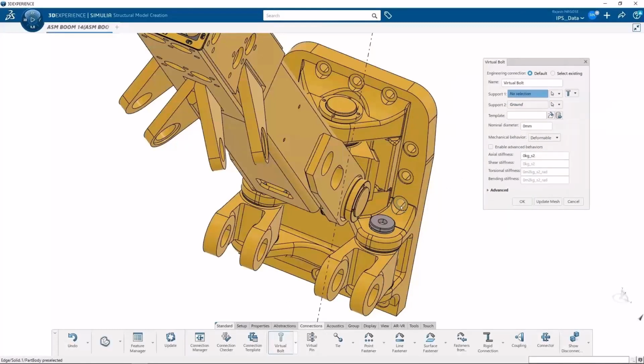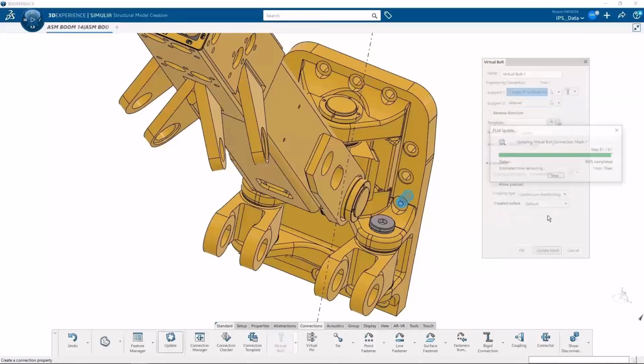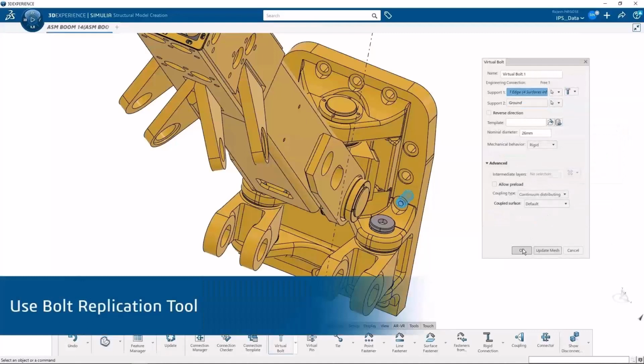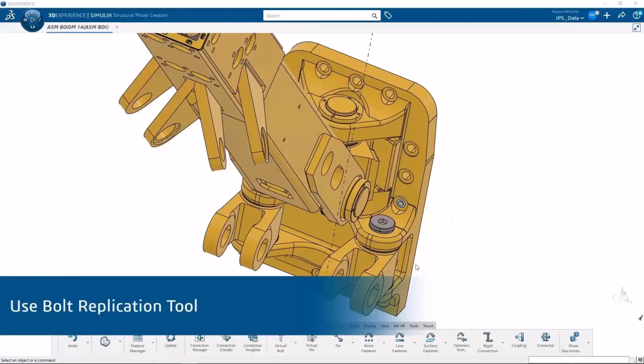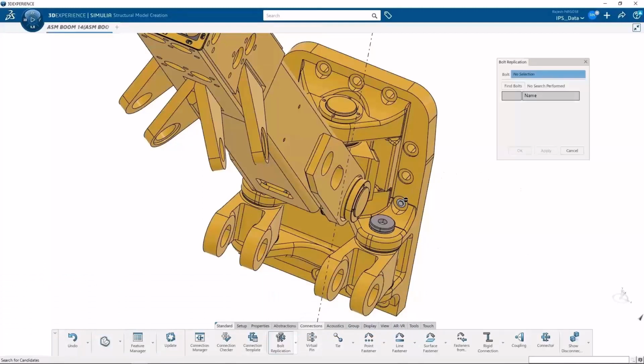I don't want to actually simulate all the bolted connections when I could just use a bolt connector in their place and save a lot of solve time. And what you're going to find is all the connectors you would expect are here and more, but their panels have some more inputs that you could put things in that you wouldn't even have in SOLIDWORKS. So they are a little bit more capable in simulating the real world.